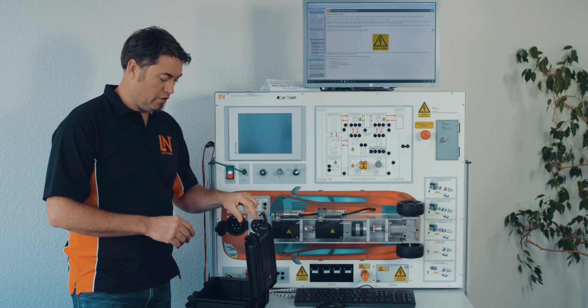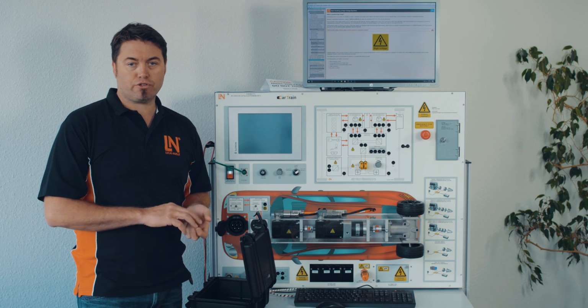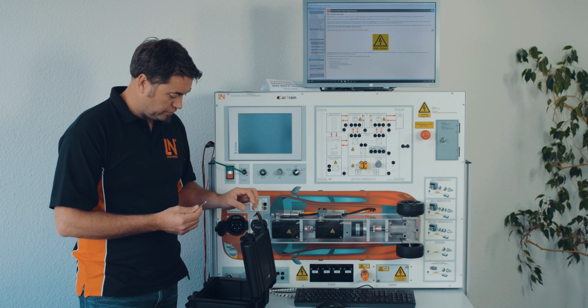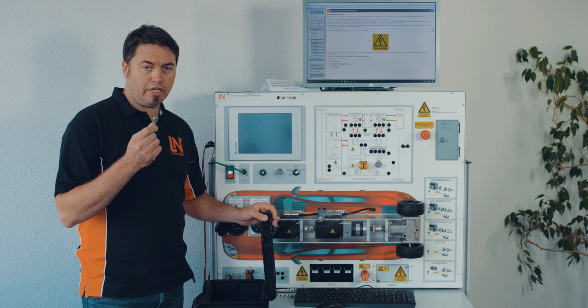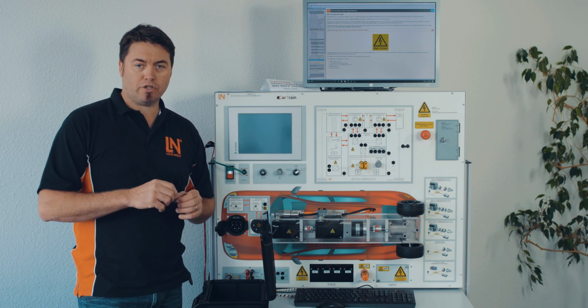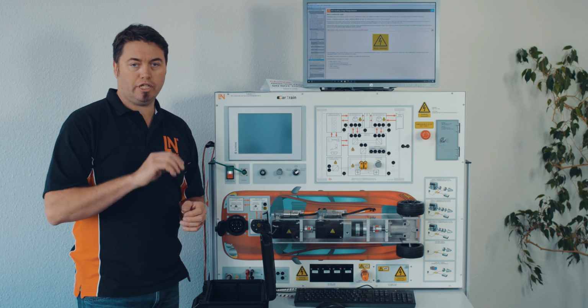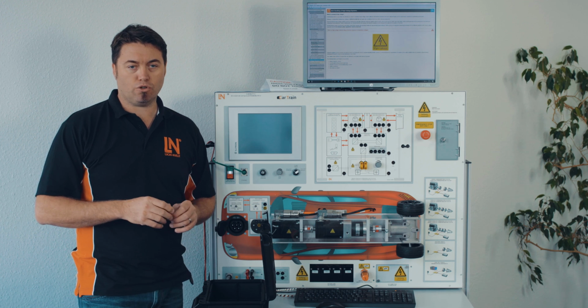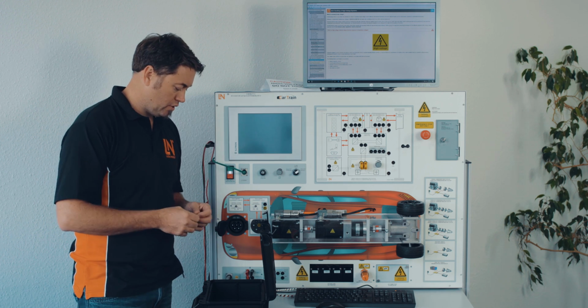But it's important that you follow the rules, either for the manufacturer or for where you work. So shutting down the vehicle, first thing is the key. If it's a smart key, a key that you keep in your pocket, where you only need to press a button, that key needs to be put away about 5 meters or 15 feet, thereabouts.